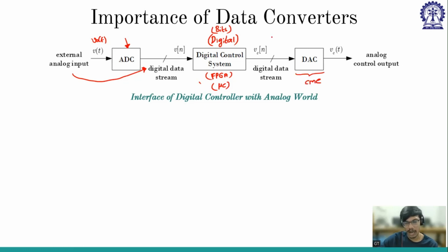So whatever I reference of n we have, and this I reference of n is, say, in bits, 10 bits. You cannot compare that with any analog signal, right? Say we have a comparator. Here we have IL, which is analog, and here we have I reference, which should be compared. So this is analog, because we are using an analog comparator. So input should be analog, as well as this other input should also be analog.